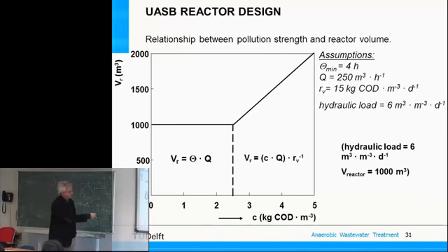This means if the concentration drops to 4, we immediately require less volume of reactor. Less organics with the same loading capacity, so you can drop down the volume of reactor. Now, you can lower further the concentration of the incoming flow, and directly you will need less and less volume of reactor. Now, you drop down with the volume unless there is a certain point in which the hydraulics are more important. If you would reduce your reactor volume to a very low volume, lower than the minimum HRT, you will lose the sludge since you're rinsing the sludge from the system.